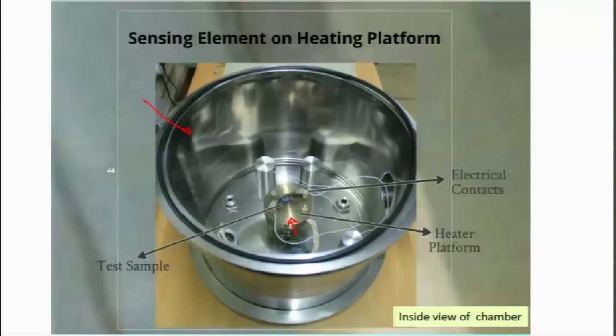So, there is also going to be an air inlet and outlet, where there is an evacuation step followed by a carrier gas, which would otherwise be an inert gas, in which we can selectively inject, through very precise mass flow controllers, ppm levels of hydrogen. As the concentration in the chamber varies and we allow some diffusion time to happen, we observe the response behavior of this element based on such changes.